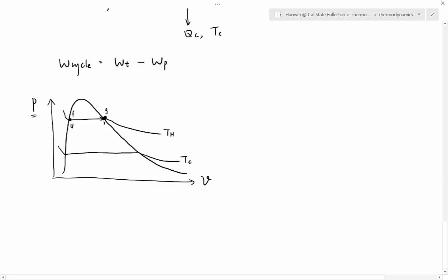Because it is expansion, pressure must become smaller, so go down. Next one, it's an expansion process, so the x-coordinate, specific volume, must become bigger, so to the right. So 122 must go down and to the right. It's a curve, slightly curved. Okay, 122, slightly curved.